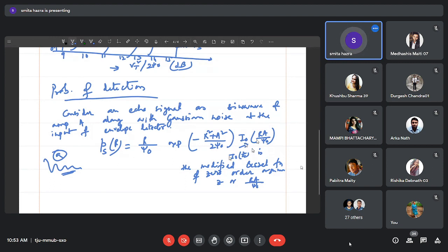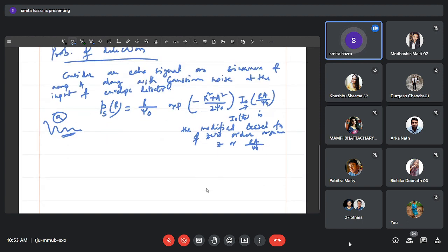So this is valid only where the echo from the object becomes very prominent, creating a contribution over this one, and the existence of that thing is there. Okay. So what is the probability? This is the PDF. So what is the probability of the detection? To get the probability of the detection, we have to integrate this density function within the proper limit.